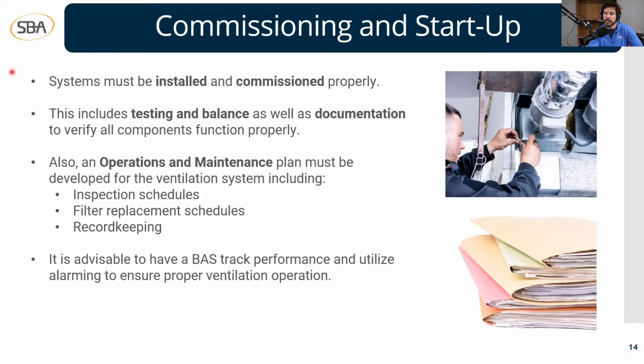Now we need to follow that up with some maintenance. So the ongoing maintenance that usually happens with this, and some of these questions are, how often are filters changed? Monthly, bi-weekly, yearly? We need to understand that. We need to keep a record of that. Now, another question we have is, are the damper motors tested?